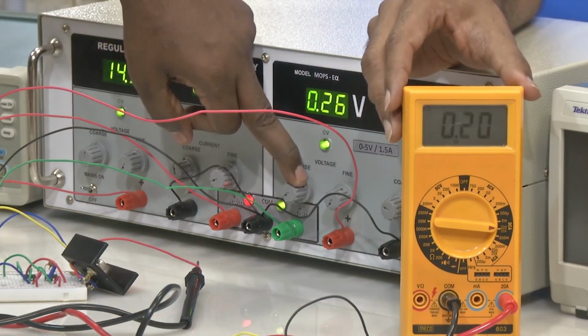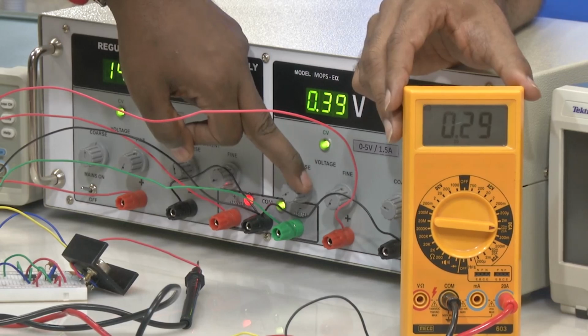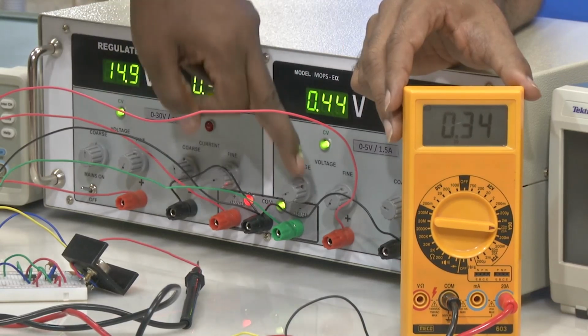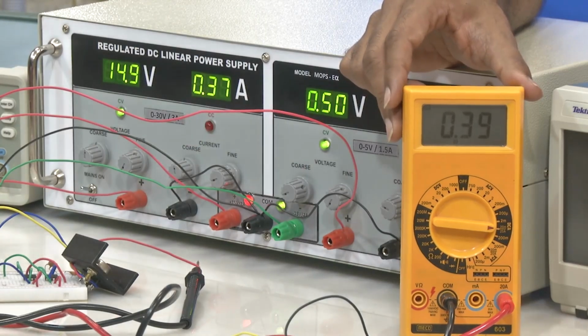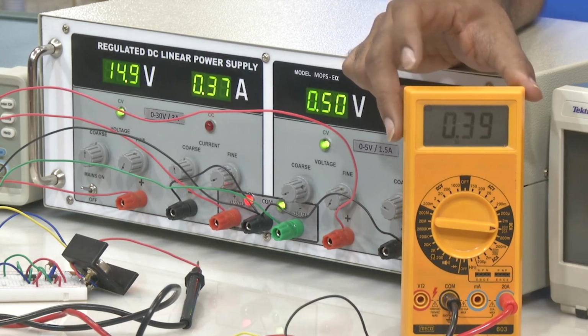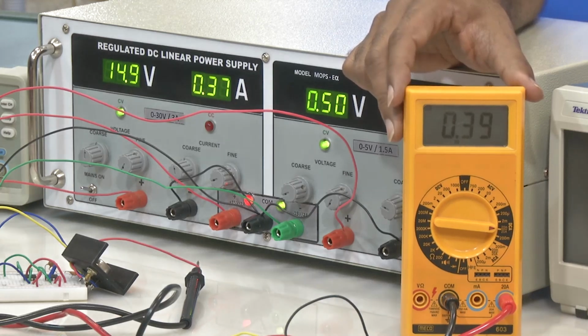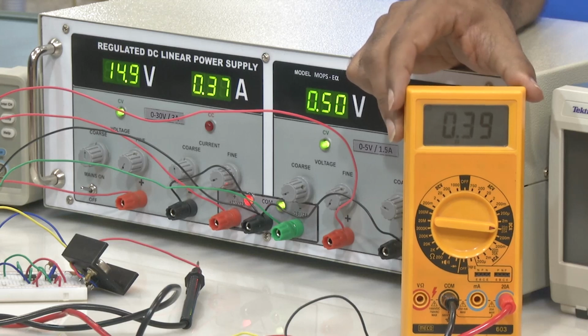The main point that you have to note is that you have to use a power resistor, and you have to use a power transistor with a heat sink. You can see at 0.5 volts we have 0.39 amperes. Thus, this is the way that you can design the voltage to current converters, alright. I am not writing it down on the screen, but I am showing it to you here how we can implement a voltage to current converter, and how we can see it working.